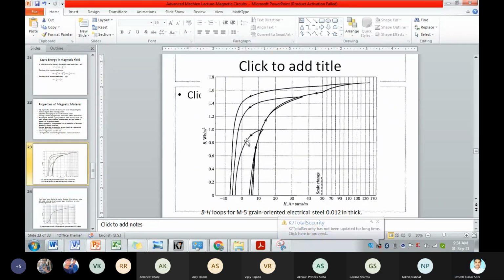So this is only the first quadrant part of the hysteresis loop, that is the DC part. Okay, so if you connect all the peak points of these hysteresis curves, like this peak point from where you had written, suppose from here 100 ampere turns, from here you were reducing so your peak point was this, from where your graph starts to return. Similarly, another peak point is this, another is this, then here 0 comes.